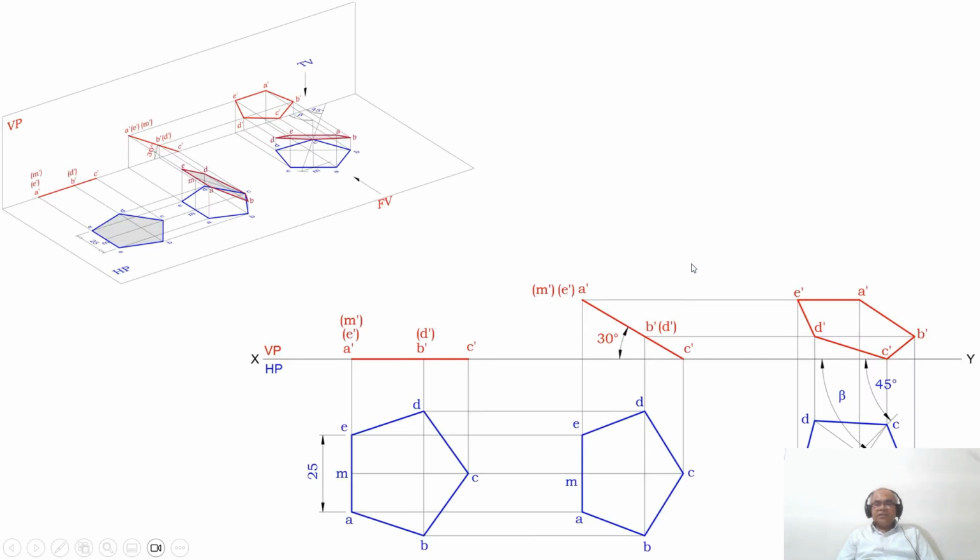Now how to do that, the third position front view or top view now. So here first we are going to consider any point and draw a horizontal line, and you mark that point as C. With respect to that point C, with respect to the horizontal line, by using the protractor, you measure an angle of 45 degrees and draw an inclined line.